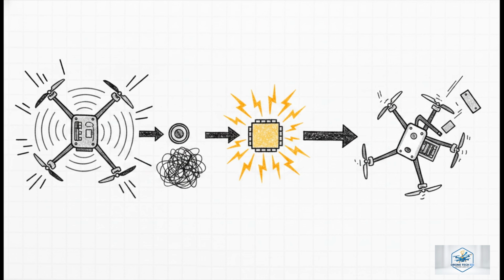And all of this brilliantly illustrates our core thesis today. A drone requires profound multidisciplinary integration. You can't just slap parts together and hope for the best. Think about it. If your carbon fiber skeleton is too rigid, it causes structural resonance. That mechanical noise travels to the gyroscope, causing sensor aliasing. The flight controller then sends panic signals to the nervous system, the motor muscles vibrate violently, and the entire system just falls out of the sky. The mechanics, the electromagnetics, and the processing power must be perfectly co-engineered in absolute harmony.